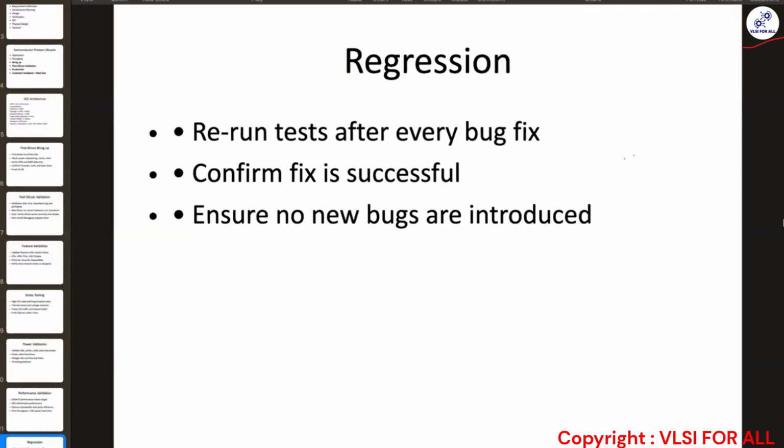In the debug part, whichever logs you have attached, you analyze them. You understand, okay, this could be the problem. Sometimes you may need to co-debug with other domain owners, right? Other domain owners meaning, consider it is a display issue. You connect through your Type C port, and then you are facing an issue with your display. It can be a Type C issue, and it could be a monitor issue, as in a display issue, meaning a graphics issue also. So you may have to include those particular domain owners as well and co-debug with them.